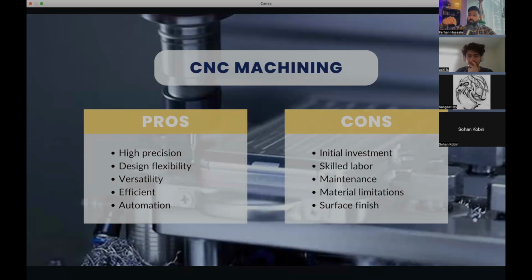What you have initially is what's called a 3D CNC. You don't really call it that, it's 3-axis. We have one cutter tool coming in one axis. It moves, for example, in the X-axis and the Y-axis, and then it moves up in the Z-axis. So you can have this 3D shape in 3 axes.